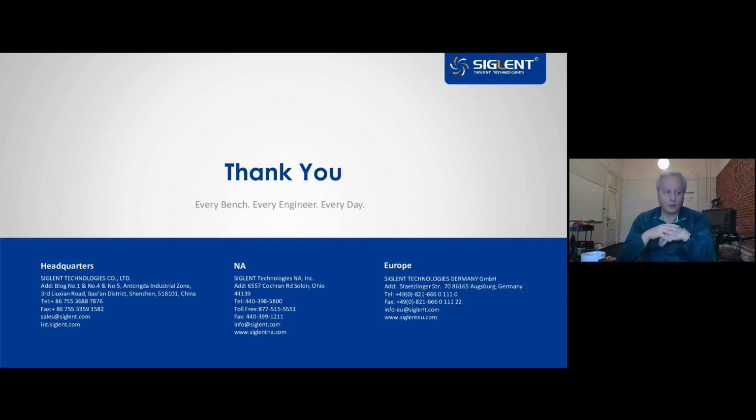Yeah, I think this is obviously an important trade-off for everyone, right? So I try to think about the use case, the application requirement to start with. Go through part of this process that we did, and then you could find a set of tools or a number of scopes that will meet that need, right? And you can compare them from a value perspective. And then I think the important thing to think about is the flexibility that you might need going forward, right? So the things we tend to pay for in an oscilloscope are memory, sampling rate, bandwidth, the top level specifications. The big jumps there are where the cost typically comes in, right?